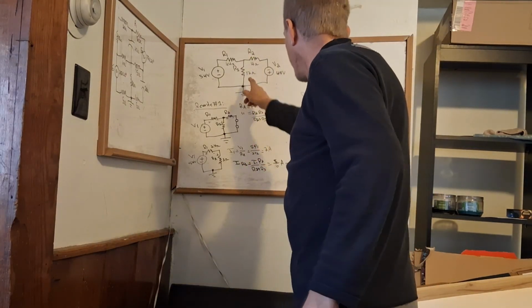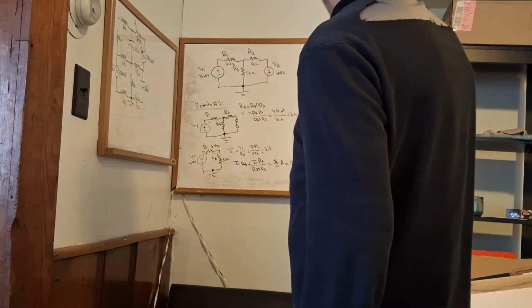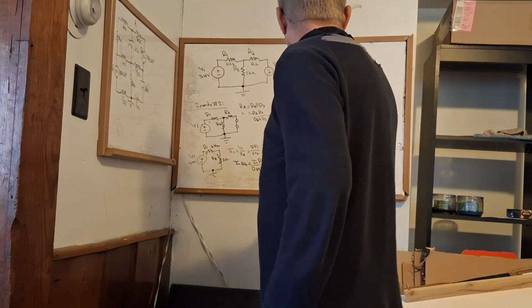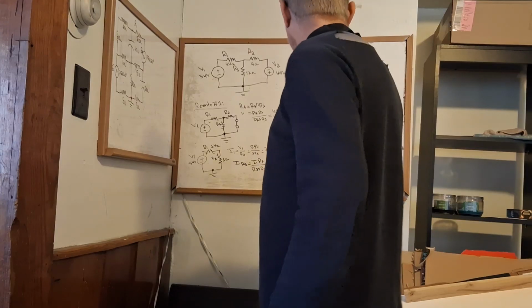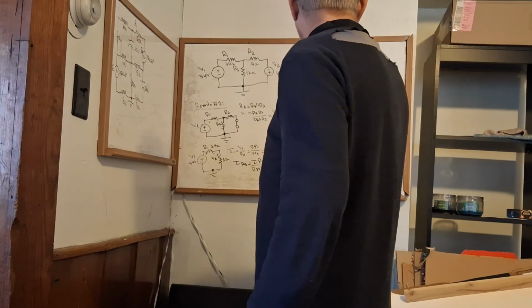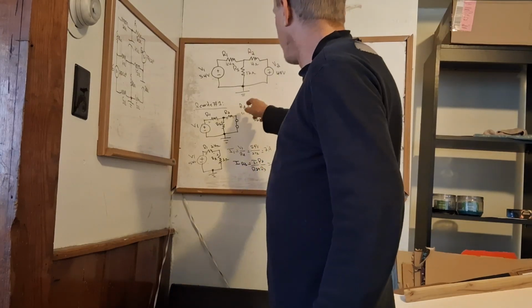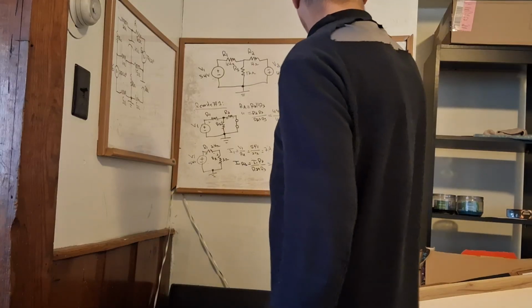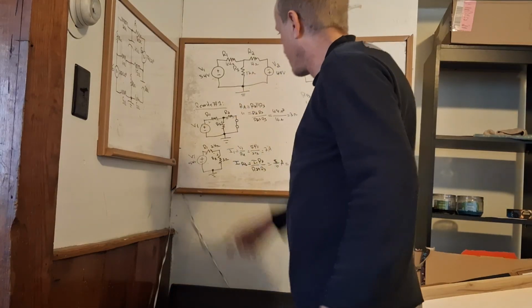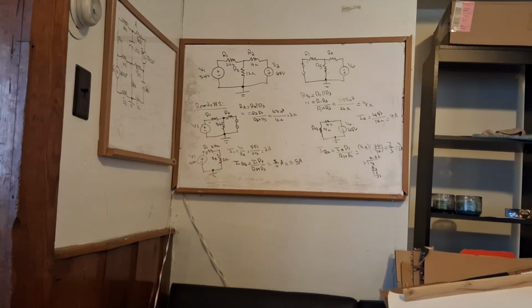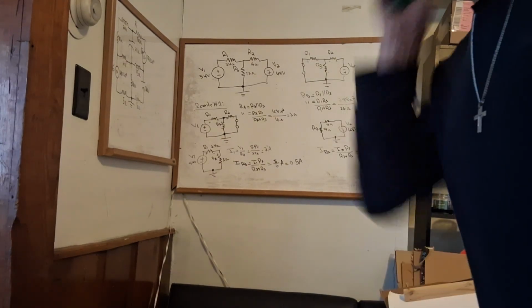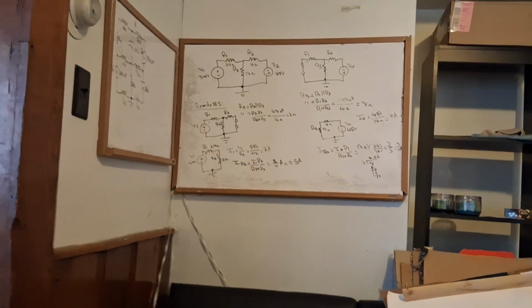And we did it for RA, RB, the same resistor. If this one's 0.5 amps and this one's roughly 2.67, then we have roughly 2.1 amps flowing through this. But let's show you the mesh analysis so that you can see a different way of approaching this, a much simpler way.